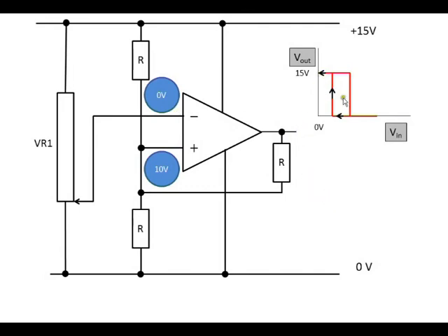So in effect, this circuit exhibits what we call hysteresis. What that means is that a different voltage switches the output from high to low than the voltage which switches it back from low to high, and hence we get this Schmitt Trigger type characteristic shape, which you often see written on components to signify that the circuit is behaving as a Schmitt trigger.